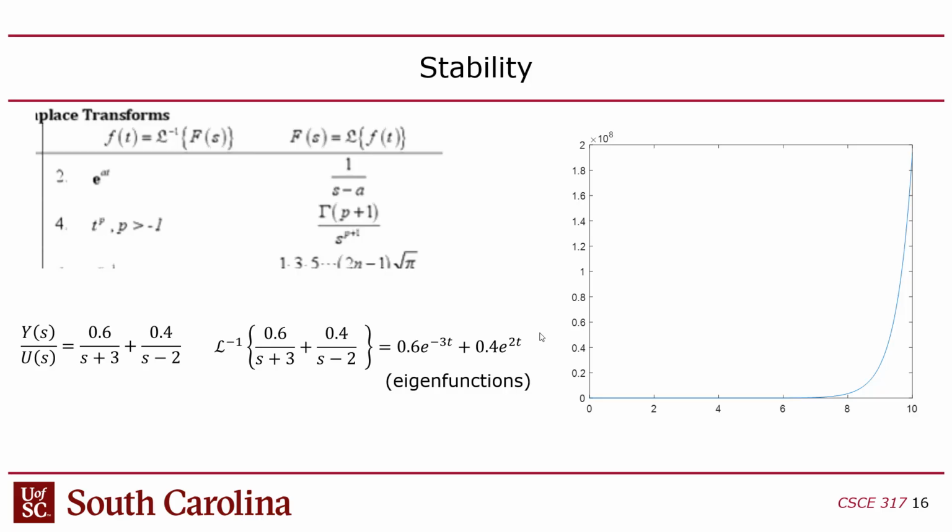But what's even cooler is that you actually get the real step response. That's literally what would happen if you hit that transfer function with a step. So you're not just learning that it's unbounded. You're learning what it actually will look like, like where the knuckle of the curve is, where you get unity gain, where the slope becomes 1 and it shoots up. So you get a unity gain point here. But anyway, that's how you can do an inverse Laplace transform. I'm out of time.